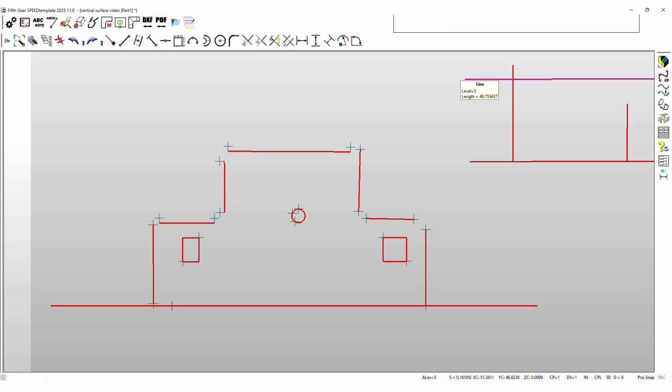Now we're going to take a look at trimming. This is where things start to vary a little bit. Trim first, trim both, smart trim both. These are the main trims, if you will, the ones that you're going to use the most. Trim first is going to trim or change the first thing you click on. So if I click this and then I click this line here, you'll see it will extend it to this line. There we go. I can do the same process. If I click this line and this line again, it will cut off the excess. So it trims or extends the object.